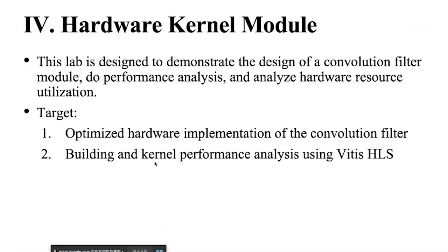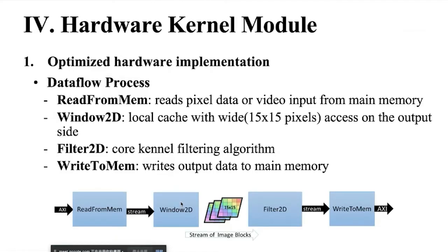And then in this lab, we're going to optimize the hardware implementation and build the kernel using Vitis HLS. The first method to optimize the hardware is using the dataflow process.